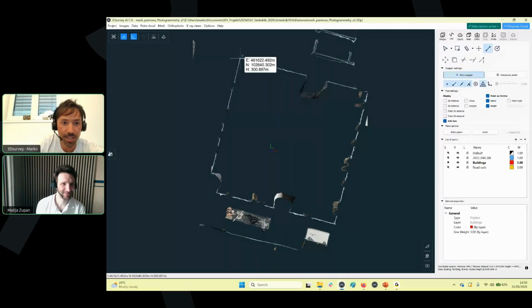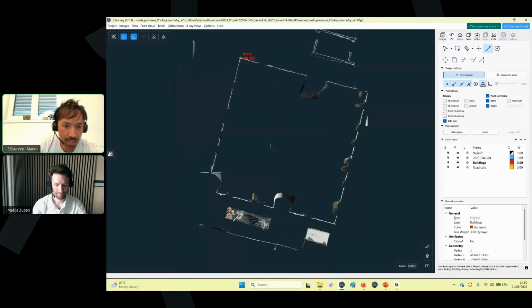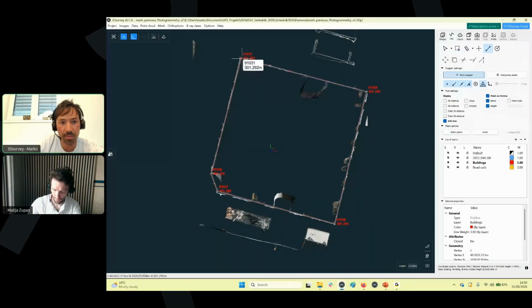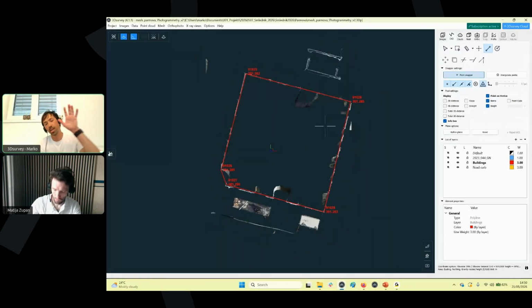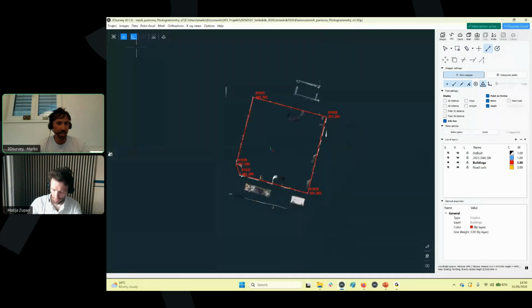That's something to witness. Okay, now we are with the points here. I will show this with the points now. So like that. So you just go and click. Here I don't have my interior corner as you saw it before. If I would help myself with the defined plane, I can create it. Otherwise, I'm directly snapping on points or mesh. And in this way, I can extract the building footprint with the help of bounding box in addition,